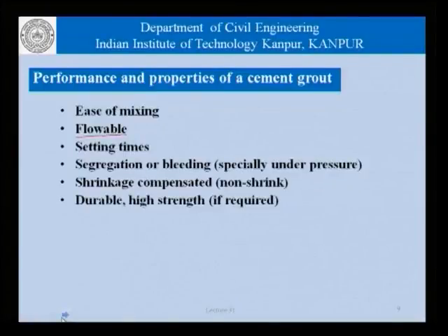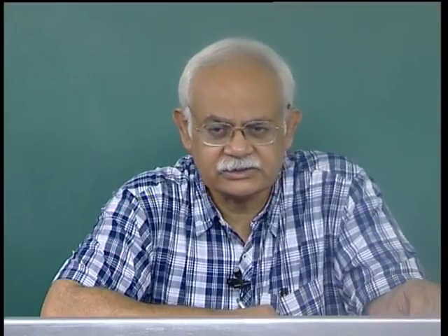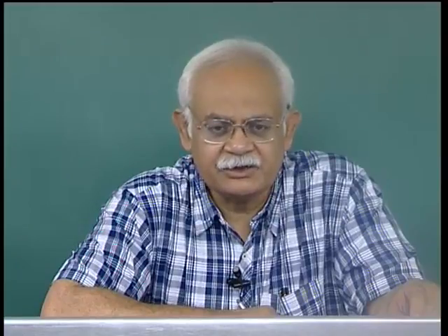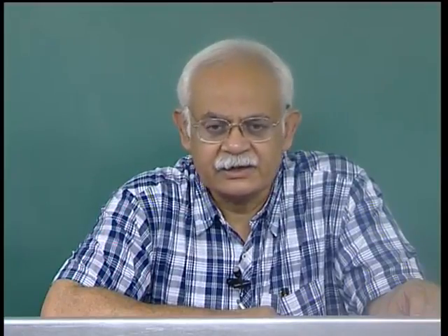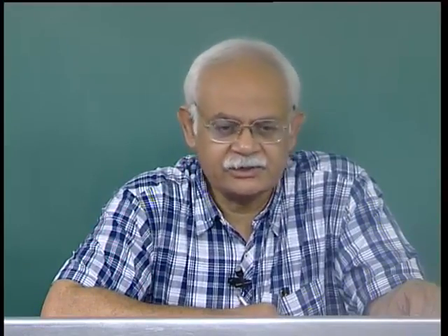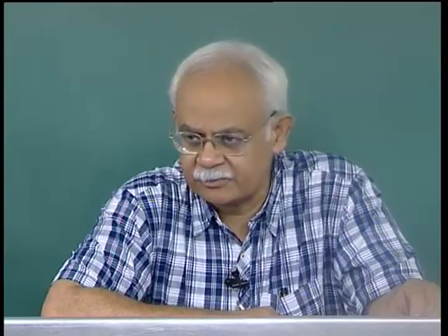Durability and strength are obvious requirements in any cement based construction, and grouting in post tension concrete ducts is no exception. We need, or we may need to specify that the grout that we use attains a certain strength at a certain point in time, whether it is 28 days or 7 days or 3 days or whatever the time be.